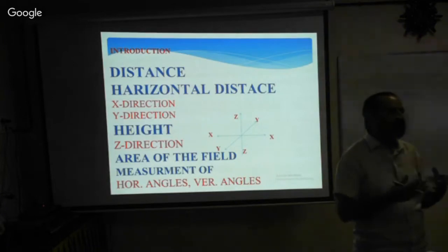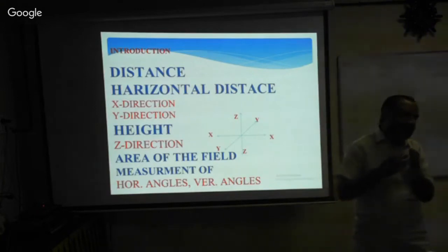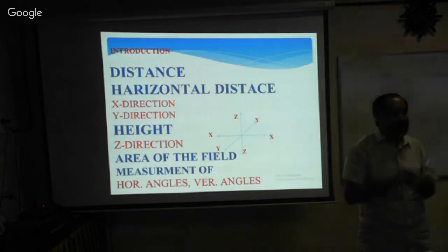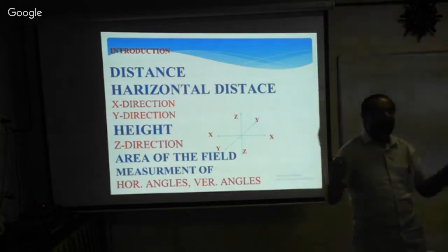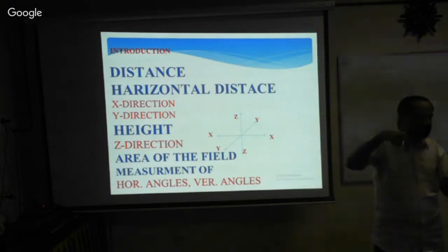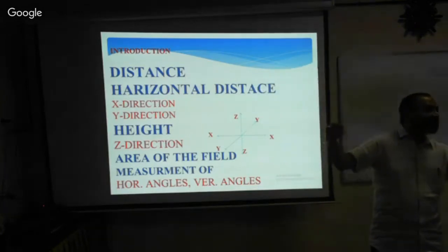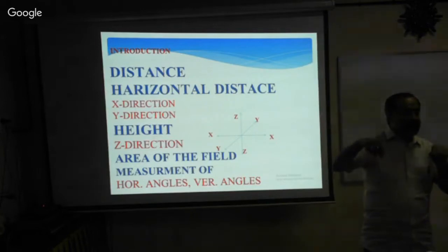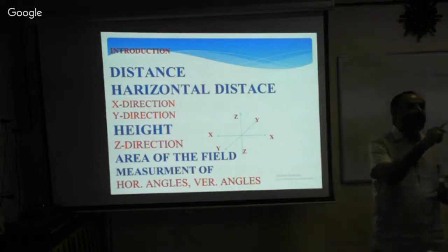If I ask you to measure the distance from one place to the other place, then we will think. Isn't it? And you know, in the construction site, the mason will explain how to find out the level from one place to the other place. That is the water level. Have you seen the water level? Water tube, you put the water, then you load the level from one end of the building to the other end. You will check the levels. The same principle is used in our leveling staff, leveling and leveling staff, level work.